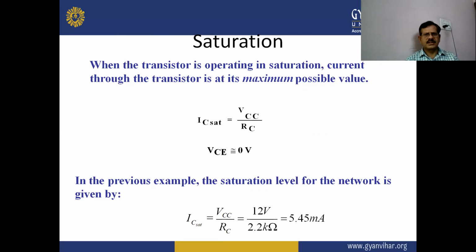And in saturation, when the transistor is operating in saturation mode, then current through the transistor is at maximum possible value. So here IC saturate will be VCC upon RC, and also VCE equal to approximately zero voltage in that saturation case.